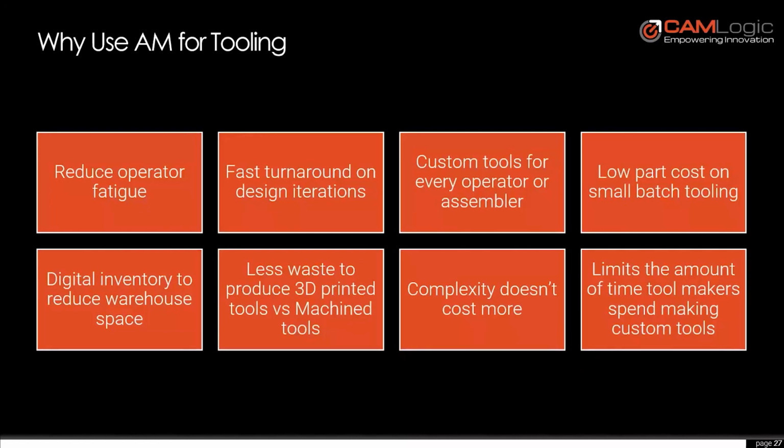The low part cost for small batch tooling. Now, again, additive manufacturing is not going to displace a lot of your traditional manufacturing processes. But when it comes to low part cost and small batch tooling, it's definitely a win. There's obviously a point where your ROI tends to fall off depending on how many parts that you're producing. But definitely for low volume production, it is the way to go.